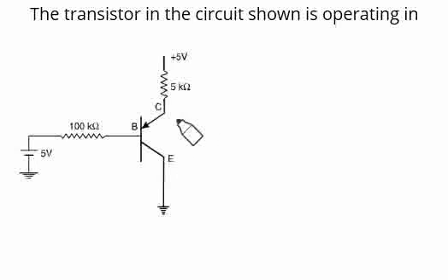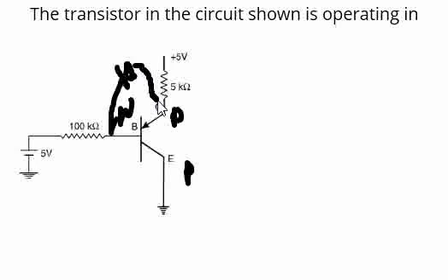the first thing that you can see is this is a PNP transistor, right? This is P, this is N, and this is P. So you can think of this particular base and collector junction like this. From the collector to base, you can think of a simple diode.